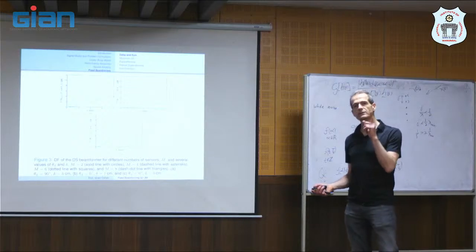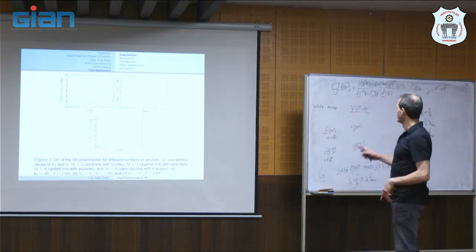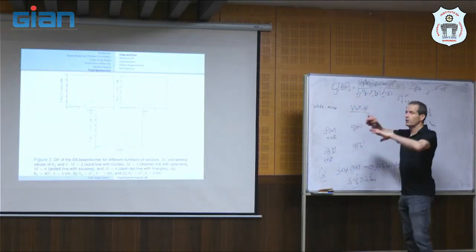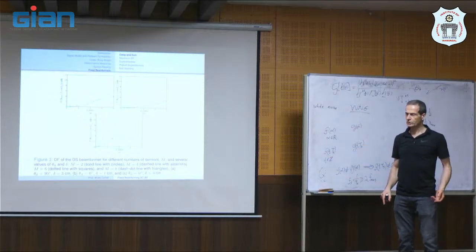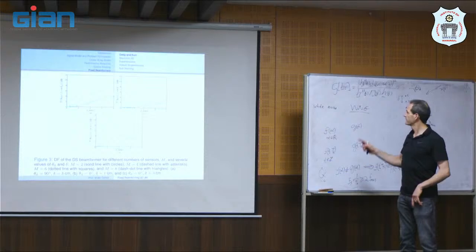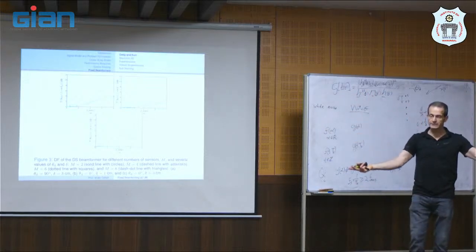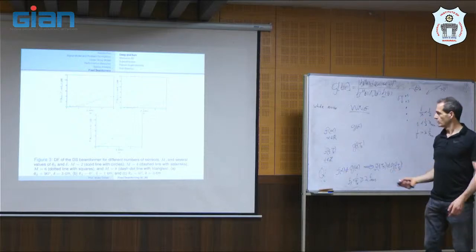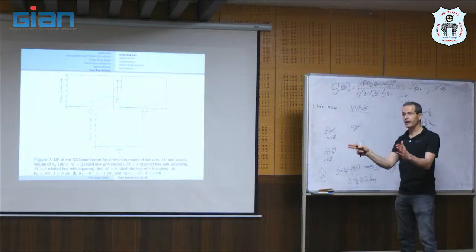The directivity is the gain in SNR when noise comes from all directions, so you take the integral over all directions. For high frequencies, you have a narrower beam width.